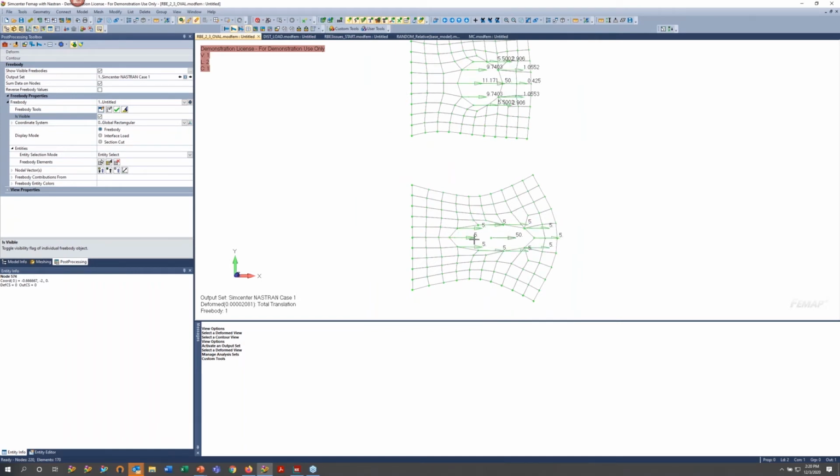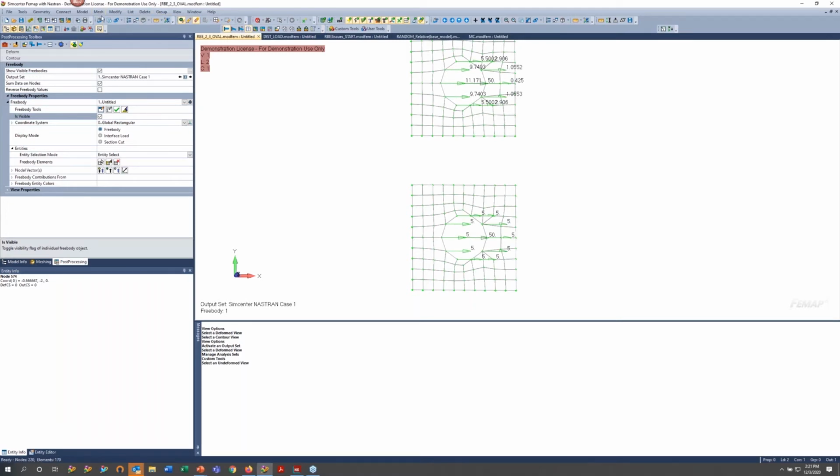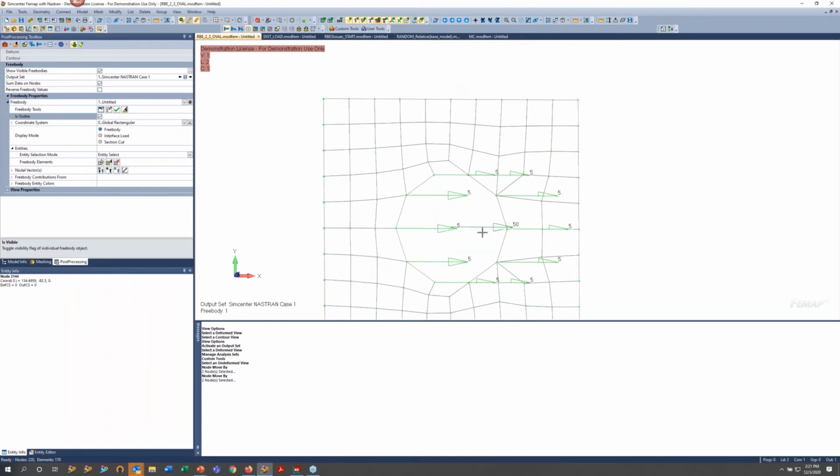So now, for instance, this is a weighted average. I'm going to go ahead and move that center node. So I'll say modify, move by node. I'll move the top one and the bottom one. And I'll move them along a vector, and I'll say where they're at, and I'll specify at that same location, but go up in the Y direction, 1/4 of an inch. So that's not very much. So I'll do that again. I'll move it up some more. So we'll go up a little bit more. All right, it moved up some. It's not in the middle, but it's okay for my instance.